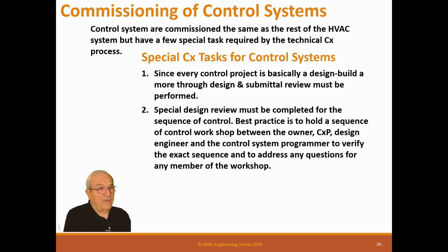Everybody should be happy, but the problem is designers tend to start with a clean sheet of paper when they're doing these sequences. And some of them come up with the darndest sequences that are very, very complicated. And with sequence of control, the KISS principle is always applied best, right? So keep it simple. Because simple means that the contractor can do it well, we as a commissioner can test it well, and the owner can operate it well. That's what we're after. So be careful about sequences. The engineer does not need to make up a sequence. Trust me, there's plenty of them for almost every occurrence out there already. And a place to start is the ASHRAE Standard 36.